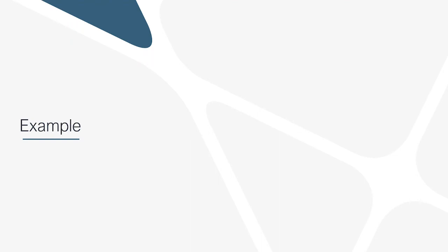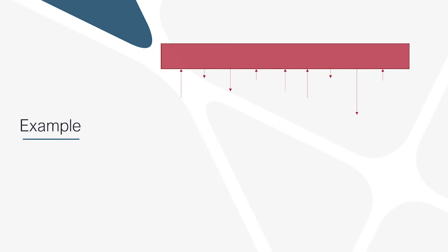Another project I was doing had a seismic analysis on a curved steel bridge, and I got some really strange reactions at the abutments. I wish I had saved a screenshot of this, but I kid you not, the pile reactions looked kind of like this. It was all over the place. This is just a made up sketch, but I could tell right away just by looking at it something was off. But I wasn't sure what was causing the problem. I remember running through a bunch of different things to try and resolve it, and I don't even remember exactly what it was that caused the issue, but I do remember that all I had to do to fix it was a simple boundary condition change.